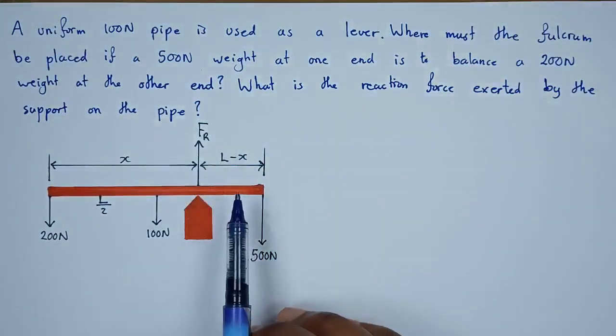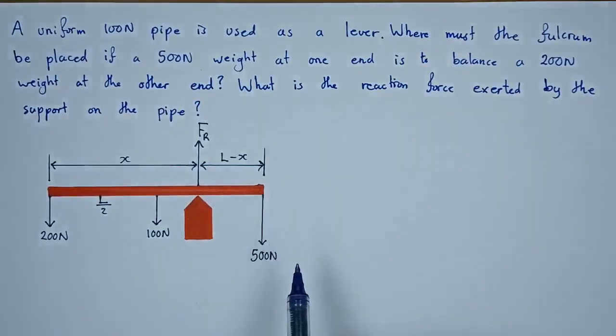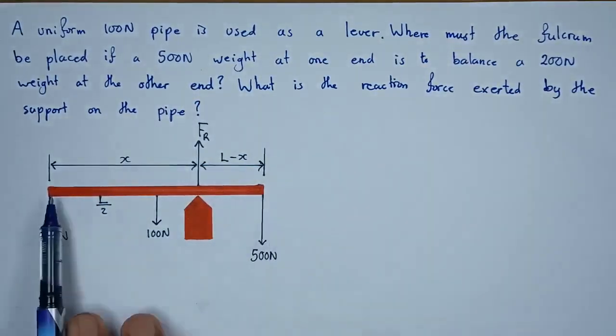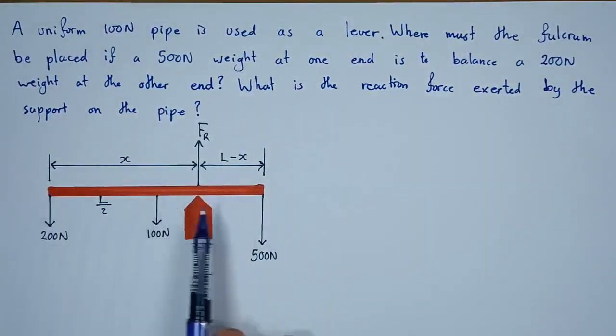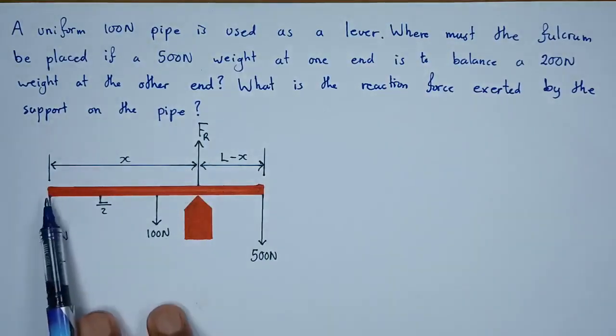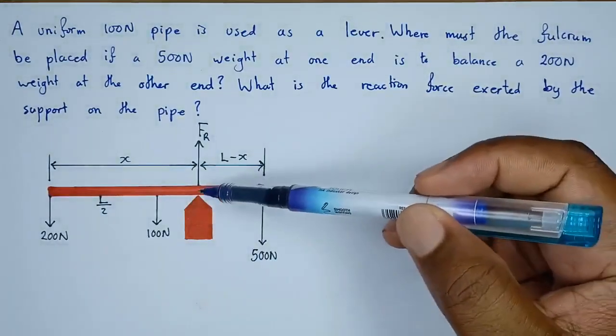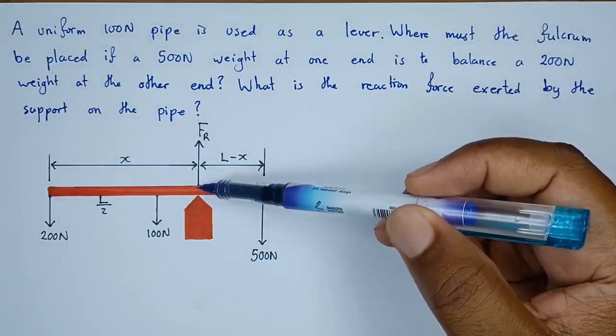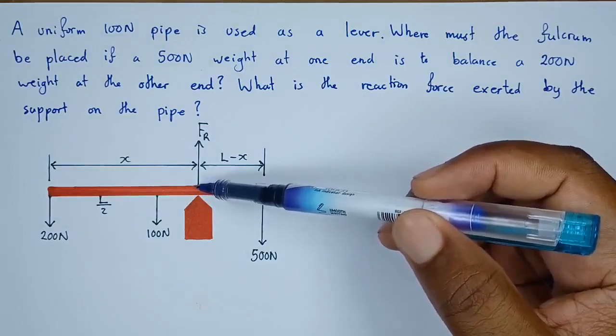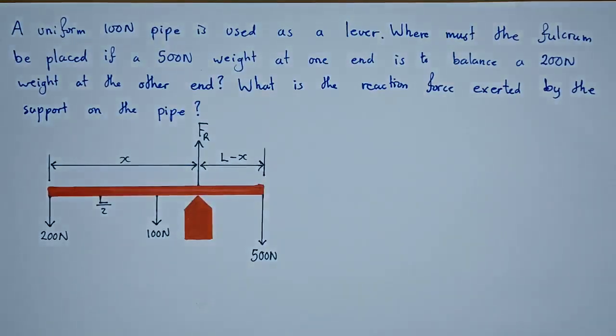So if that's the case, this is what we're going to have. Since we have forces, 1, 2, 3, or let's consider them 4 forces, 1, 2, 3, 4. But this force that we have here will produce a 0 torque, simply because this force is at the point where we have chosen to be the point of rotation. Hence, the distance will be 0 meters.